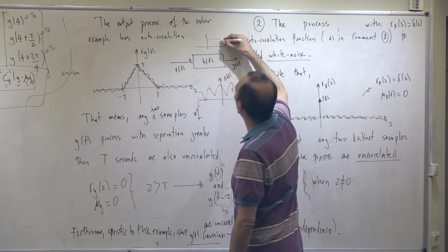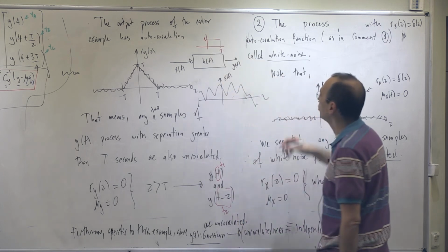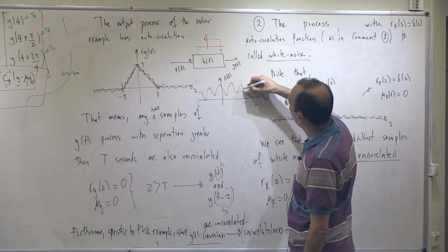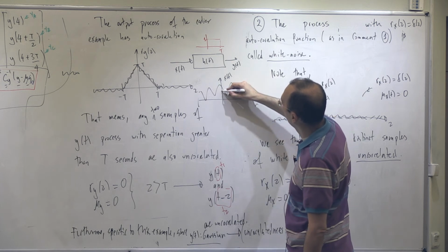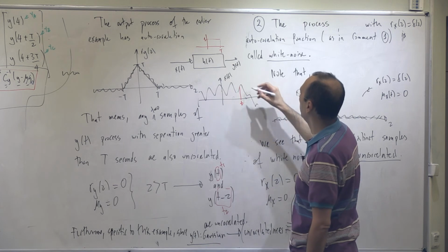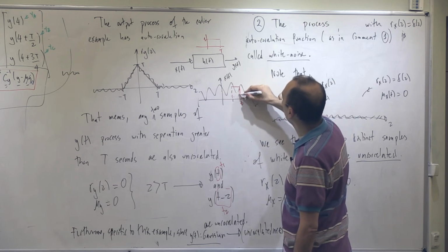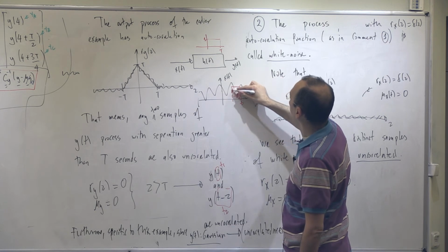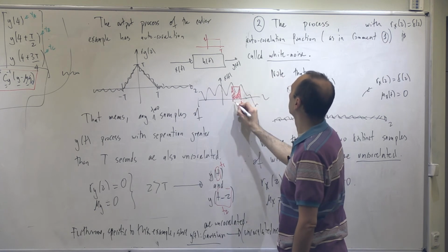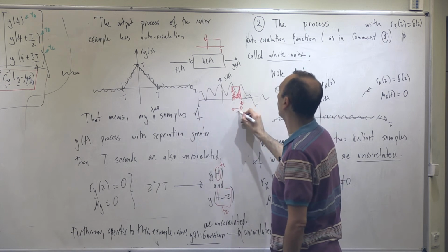The impulse response was flat in the first t seconds. So for the output at this second, y of t, you are calculating the area of this function in the last t seconds. That becomes the output, the convolution operation.